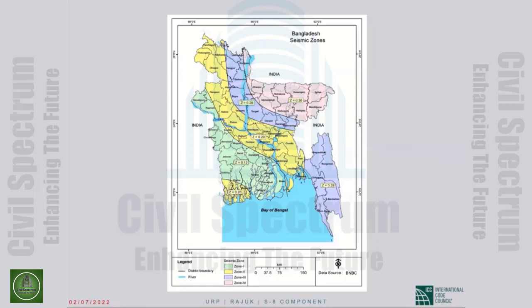Okay, Dr. Ghosh. There are a lot of questions, so I'm just going over the ones that are relevant. In your presentation today, you showed that torsional irregularity is in terms of maximum versus average displacement, but in BNBC, it is in terms of maximum versus average drift. Could you clarify this? There shouldn't be any difference.